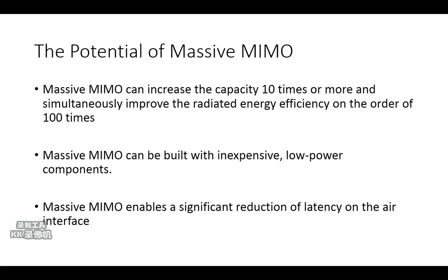If the terminal is trapped in a fading dip, it has to wait until the propagation channel has sufficiently changed before any data can be received. Massive MIMO relies on the law of large numbers and beamforming in order to avoid fading dips, so fading no longer limits latency.